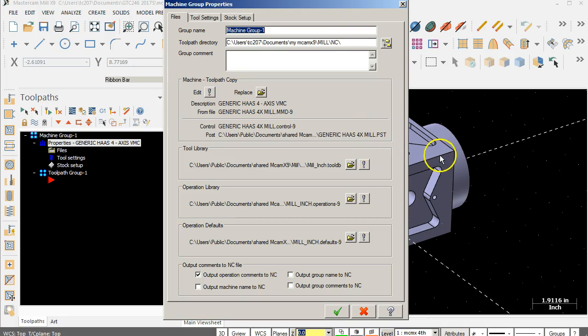All right, so if there is a critical positional axis, I should be able to hold those datums. I should be able to hold those tolerances within that rotation and come up with a more accurate part, not having to take it out of the vise, rotate it, do additional machining, take it out, and then just the additional setup and operations going through each of those sides.